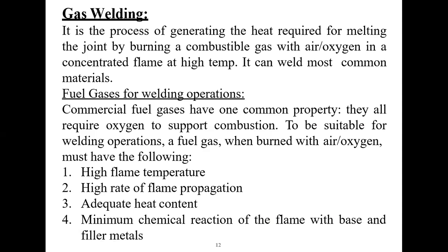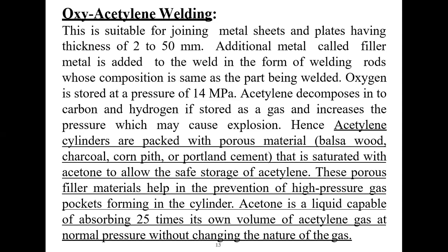But a fuel gas when burnt with oxygen must have the following: high flame temperature, high rate of flame propagation, adequate heat content, and minimum chemical reaction of the flame with the base and the filler metals. So these points we have to remember before performing any welding operation. Next is our main thing, that is acetylene welding. This is our main objective to do in our workshop. So I am not reading all the lines. I'm going to the main thing.